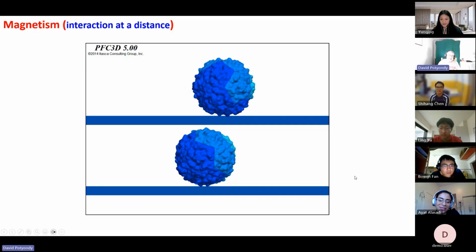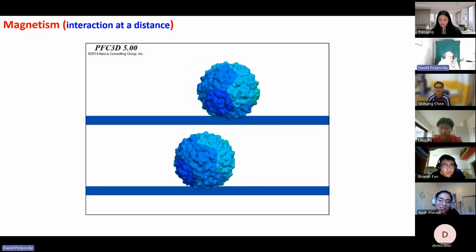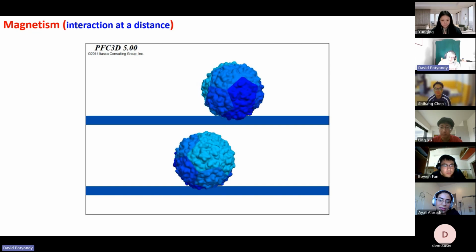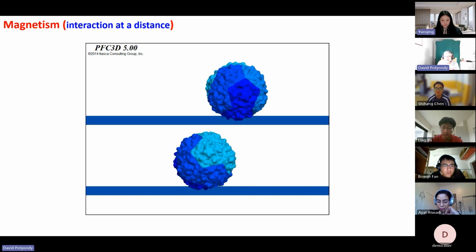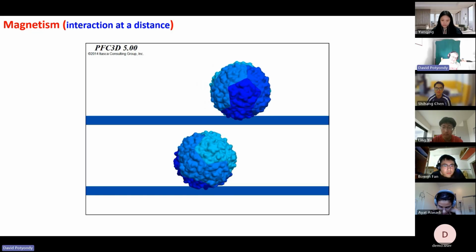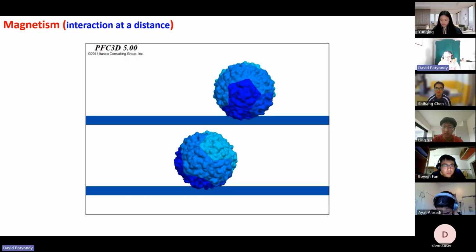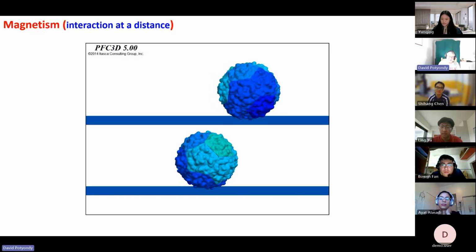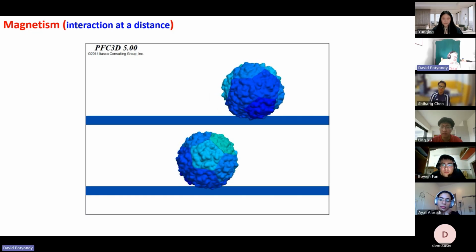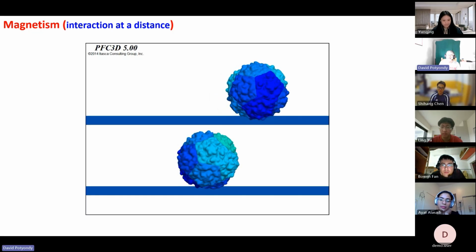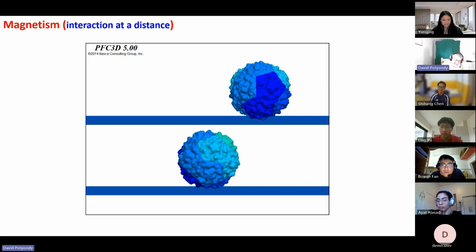I show these partly for fun, but partly to illustrate the idea and the power of the discrete element method, because you can generalize. Peter Cundall came up with the method and he was applying it to simple systems that were like grains of sand. For those systems, if you just have a Kn and a Ks and a friction coefficient and the shape, you can get really good proper behavior.